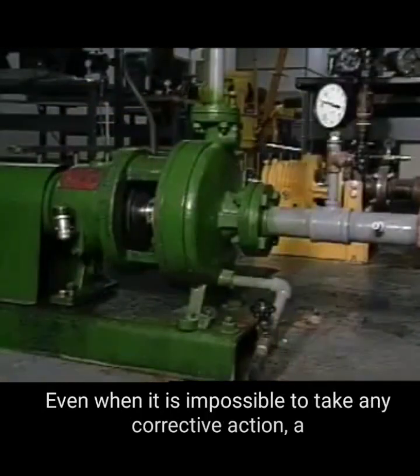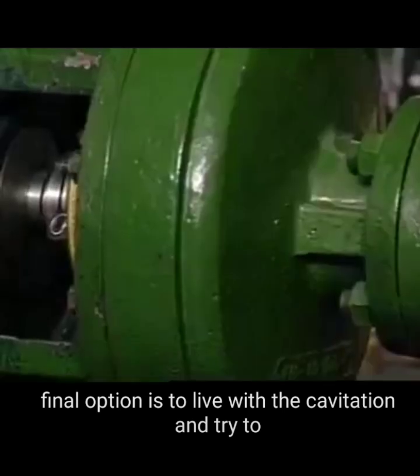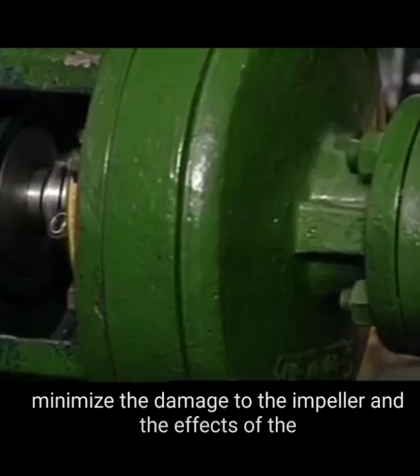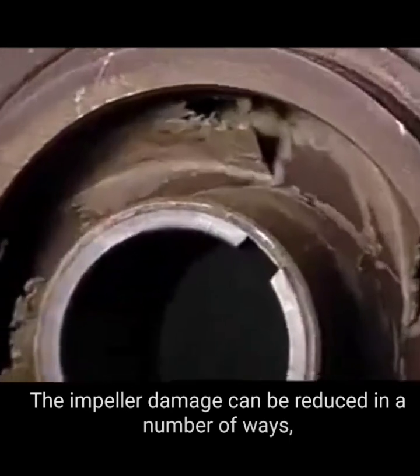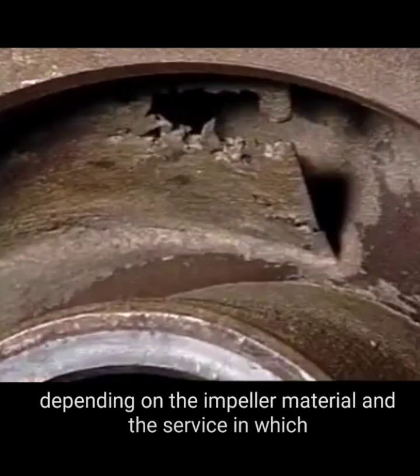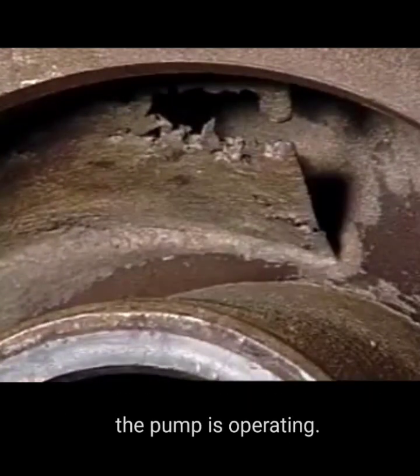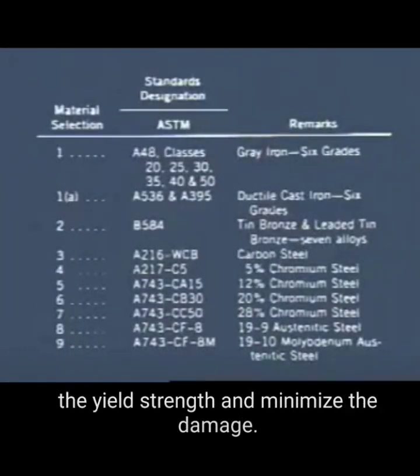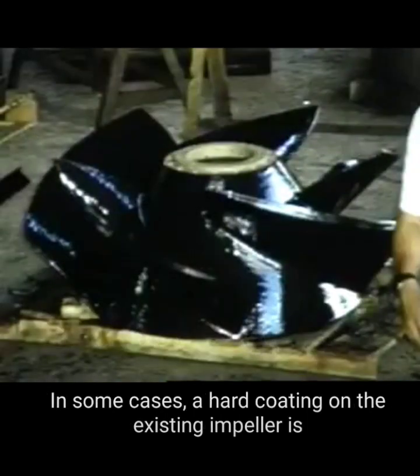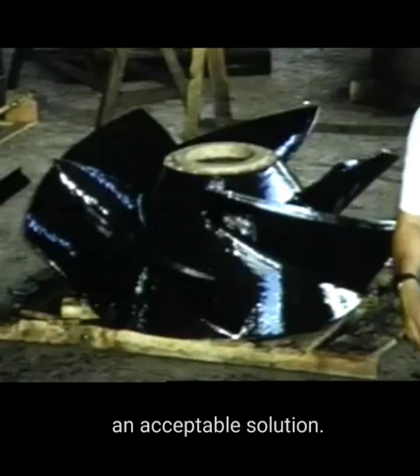Even when it is impossible to take any corrective action, a final option is to live with the cavitation and try to minimize the damage to the impeller and the effects of the vibration. The impeller damage can be reduced in a number of ways, depending on the impeller material and the service in which the pump is operating. A simple change to a stronger impeller material will raise the yield strength and minimize the damage. In some cases, a hard coating on the existing impeller is an acceptable solution.